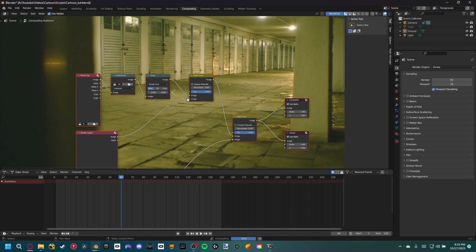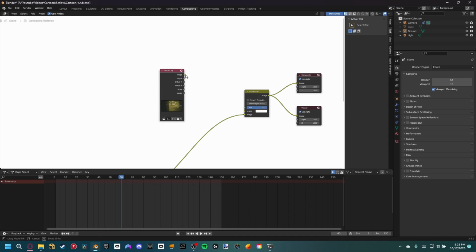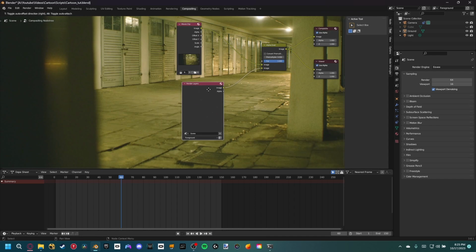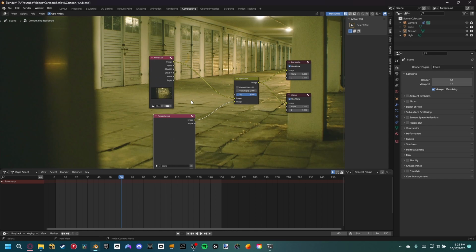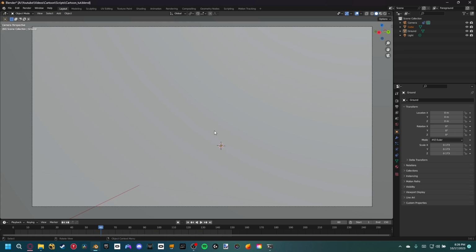And then in the compositing section, let's just go ahead and delete these 4 nodes. We're just deleting all these because it's what Blender automatically set up with us setting up a tracking scene, but we're not going to need them for this tutorial. So there's that. Now let's come back out to the layout tab. Let's Alt-H to unhide everything.